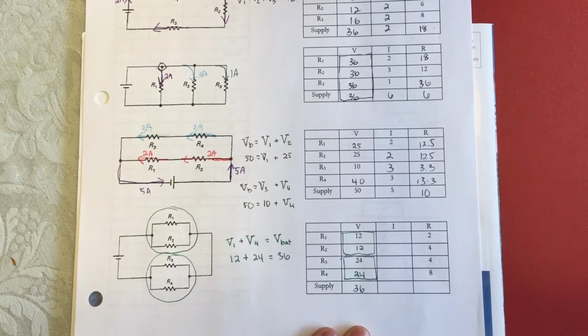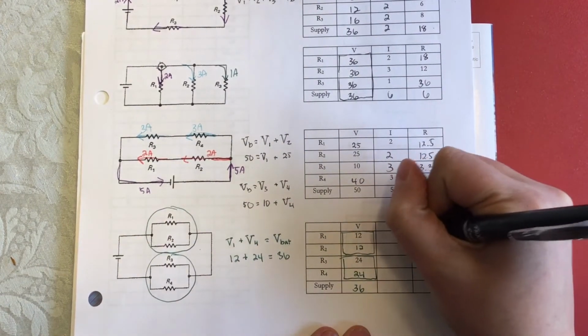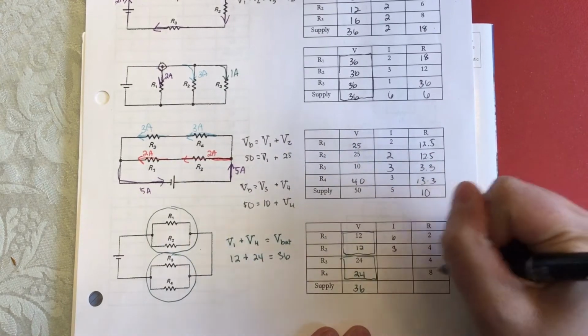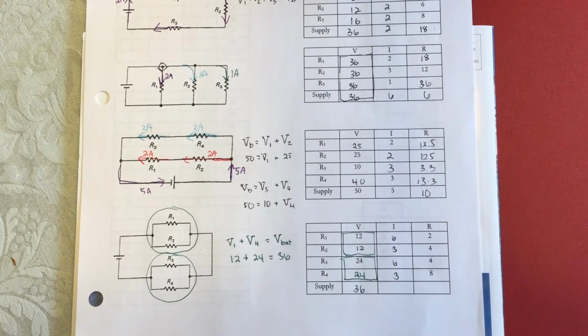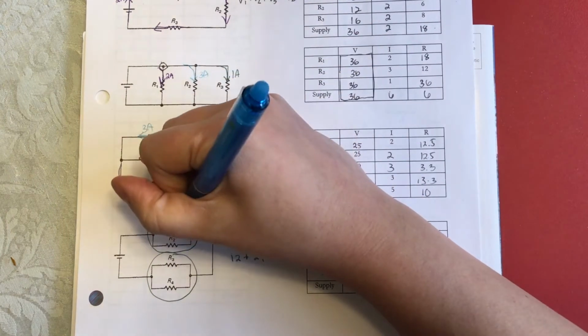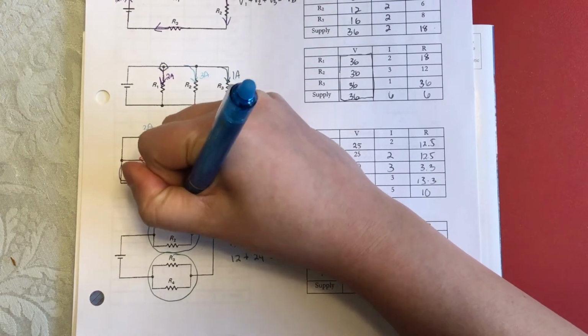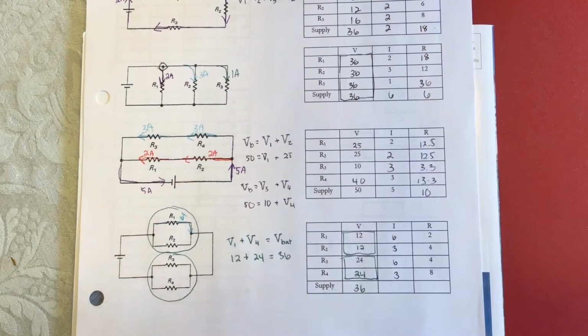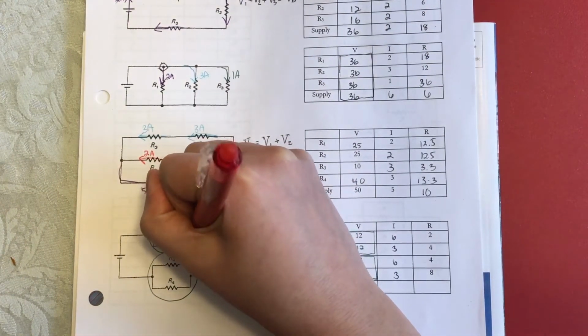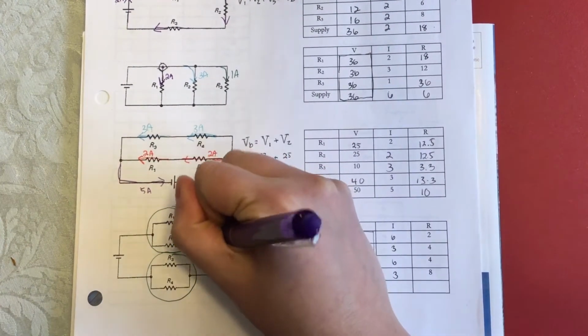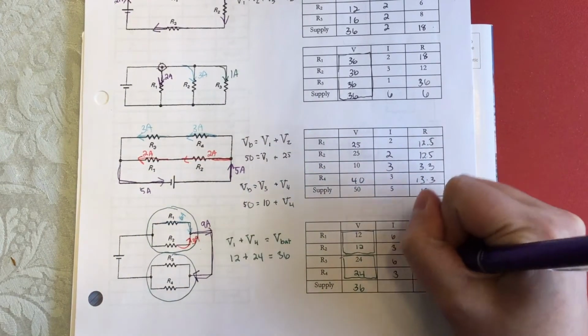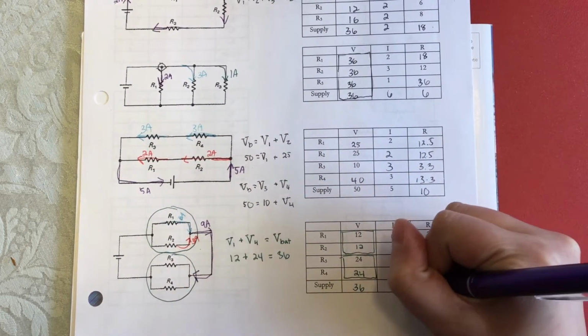Then, solving across with Ohm's law, this leaves the current as 6 and 3, and then again a 6 and 3. Using the junction law then, if you imagine that the 6 and 3 currents at any particular junction are going to recombine. This means 6 amps goes in through R1, 3 amps goes in through R2, making 9 amps total current. The junction rule makes sure that you don't double count this as 18 amps. This is only 9 amps total.